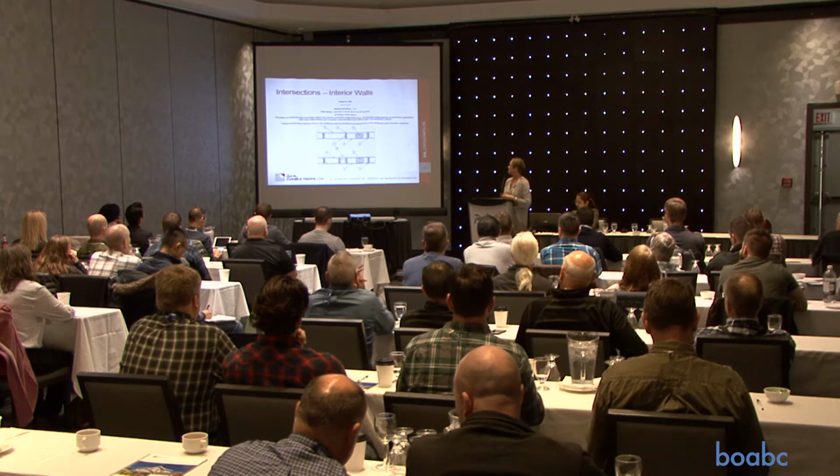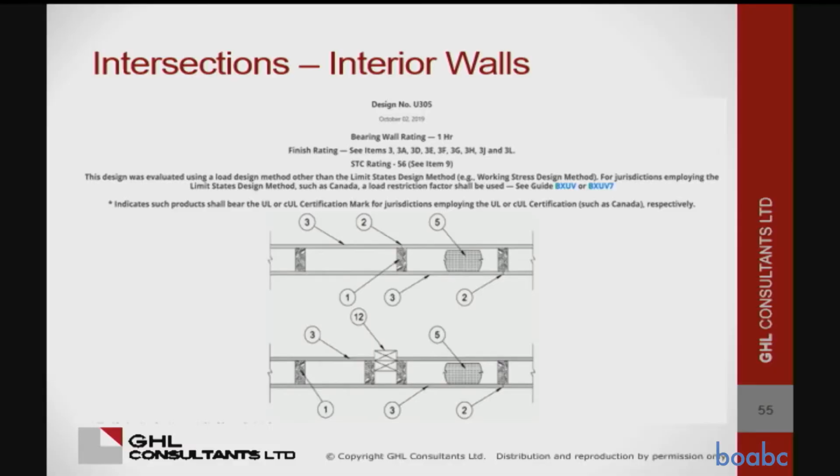Oh, I love this picture. So in this municipality that shall remain unnamed, you also have to run the gypsum board on your fire separation before you butt any interior walls up against it. And these things are difficult to just do this sort of backing during framing, because especially here, it rains half the year without stopping, right? And it's going to be outside, and you've got to get your drywaller in to do something before you're finished framing, and when does that ever happen?